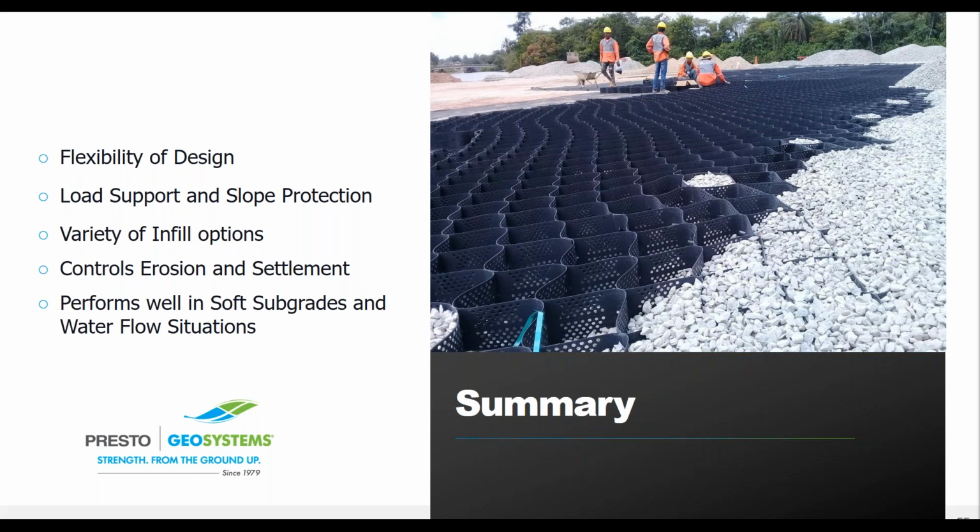Okay, so that's the presentation. So basically, in summary, the GeoWeb system can be used for a wide variety of applications for dams, levees, spillway structures, that sort of thing. And it can offer both load support applications for vehicle traffic and erosion protection against water flow and wave action. You can have a variety of different infill materials, and you can even vary those within the same project, so you don't need to be limited to just concrete or just stone. And so it's going to be the best solution for your project.